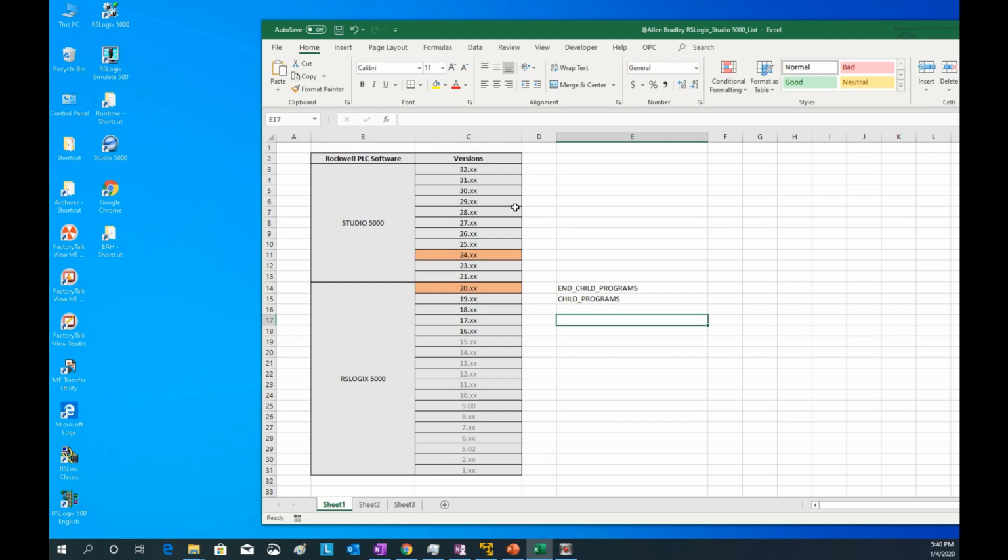It cannot be guaranteed that this cross-opening will be successful every time, but most of the time it will be. For special reasons, for example, if your higher version has special modules, such as analog input, some encoders or servo motor axes inside, then the lower version won't open or show it correctly.